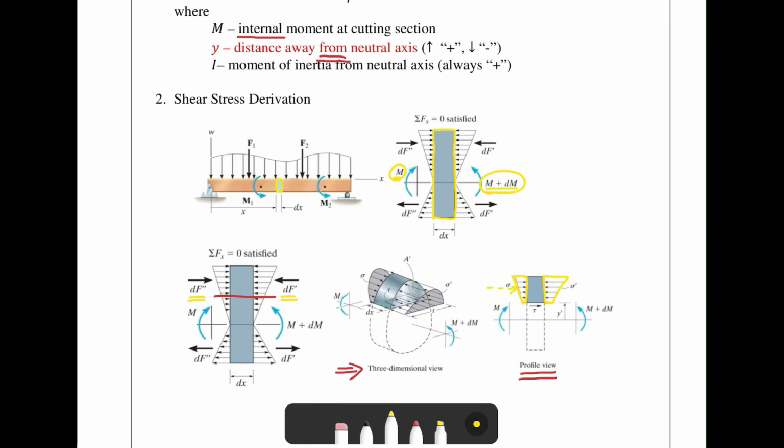So we say this is F1, and the total force on the other side is F2. You can see they're not going to be equal. Their areas are different. So that's why we've got to have something to balance it. We say this is going to be F3. That's actually the mismatch in the normal stress.